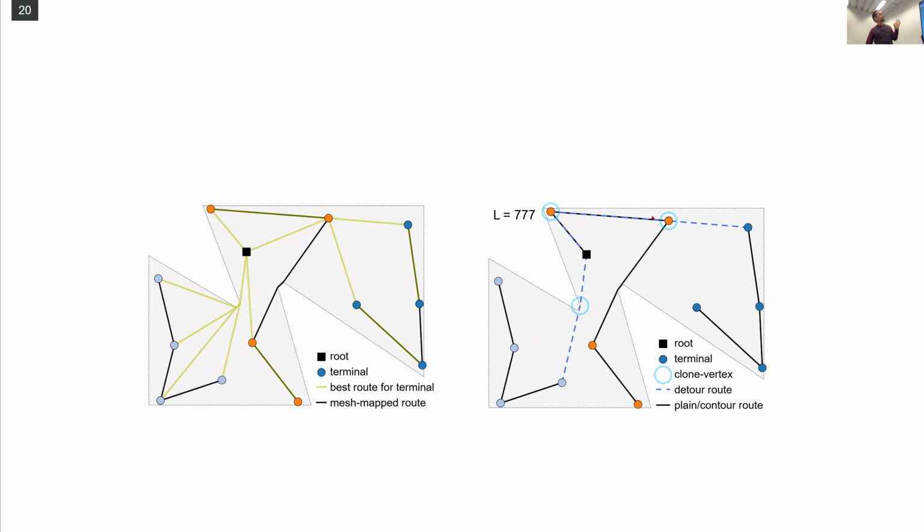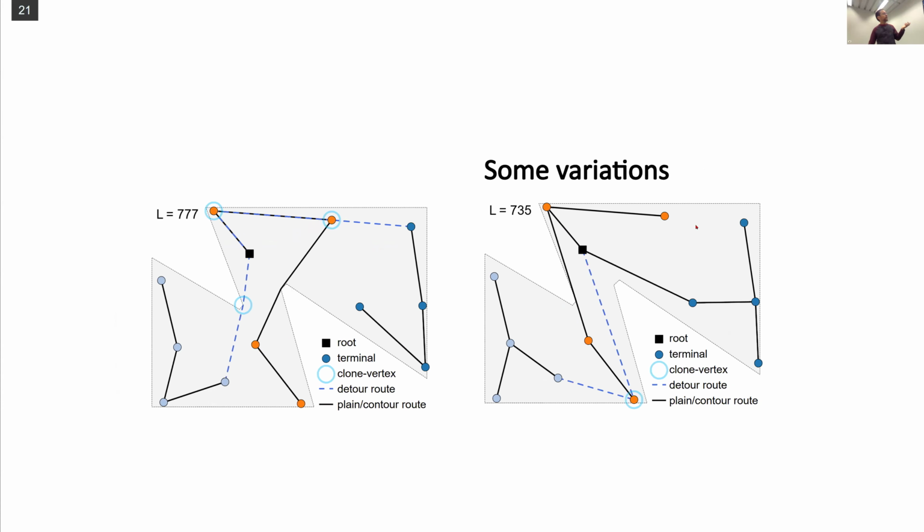This is not looking too good for an optimal layout, but that's because this has the constraint of not branching. So each string of turbines is just a path along a sequence of turbines without any forking, which is usually allowed. So if you allow forking, here the capacity is 4. You can only have 4 turbines connected to the substation on a single string. With this relaxing of that constraint, or allowing branching, you get a reduction in length.